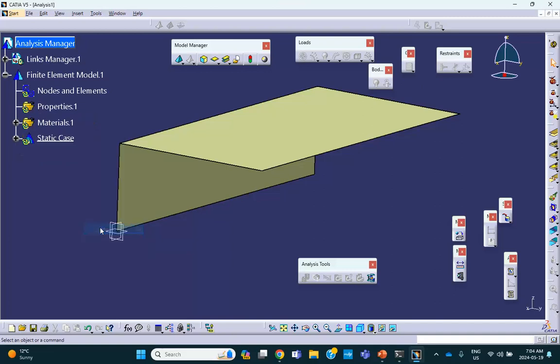So essentially, I start from fresh. I did not delete the part. The part is there. The part was meshed because CATIA sensed that there is a 3D object there, and it meshed it and created a 3D property. But I don't need it, so I delete it. I have to do the rest myself.